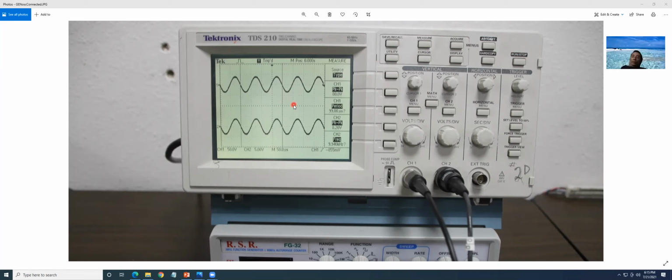And now, next thing I will be asking you, your scope probe. Normally, you set it to be by 1 or by 10. Okay? You know how to do it, right? On the scope probe, if you set your scope probe here by 1, then your oscilloscope, you must set that the same. Otherwise, you get a wrong value. So my question is, I want to set the channel 1 here by 1. How?